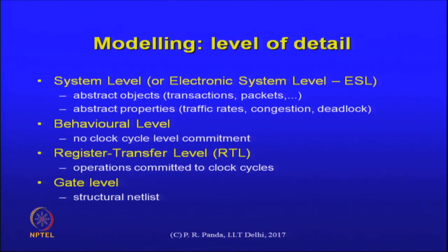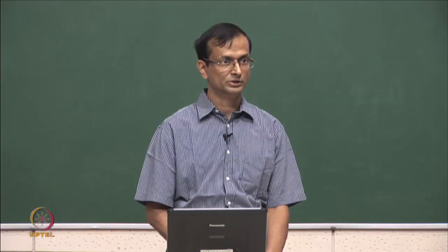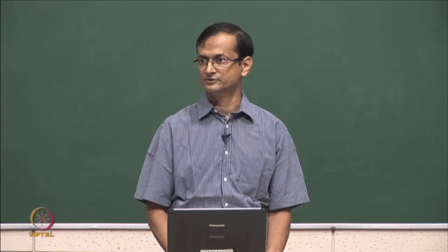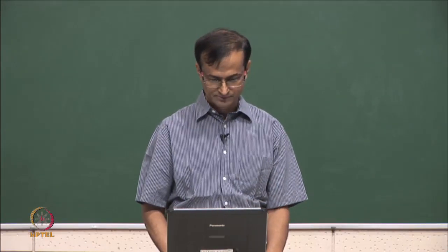We can indicate the entire computation, and we can say that all of it must be finished within a given number of clock cycles. But that is still not enough for us to produce the whole design. We have to make some further decisions. Those decisions will be part of a synthesis step. Mapping of operations to clock cycles are exercises that have already been taken when we go down into an RTL level of description. So, that is an important difference in abstraction.